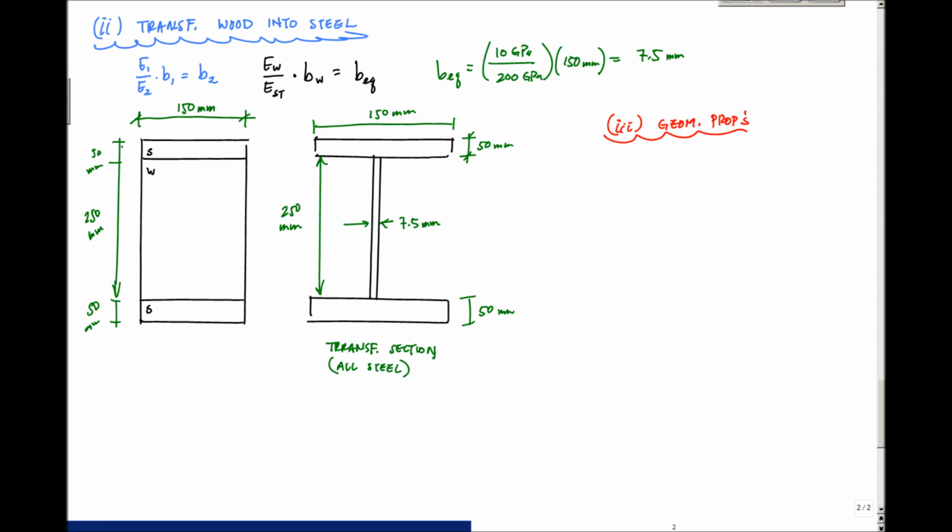So the neutral axis is at the geometric centroid, so y bar in this case, because everything is symmetric. From the bottom here, it's going to be halfway, right? This whole cross section is symmetric. So this is, let's see, 250. It should be 175 millimeters from top or bottom. Okay, so it's 175 millimeters. So our neutral axis, our centroid, is here. I'll do that in red. Why not? Bam, like this, and this is the middle, and this distance right here is y bar equals 175 millimeters.